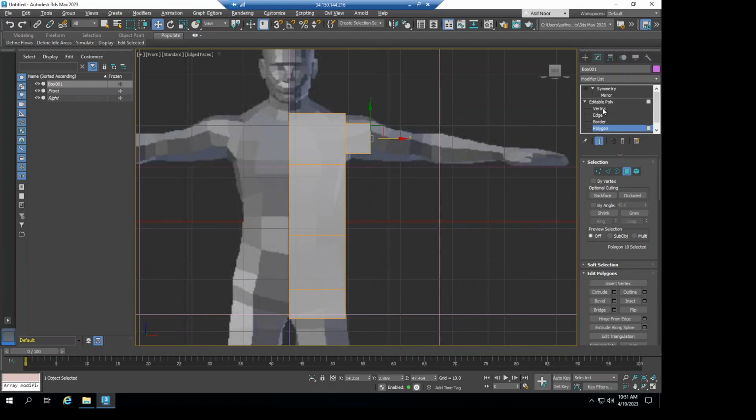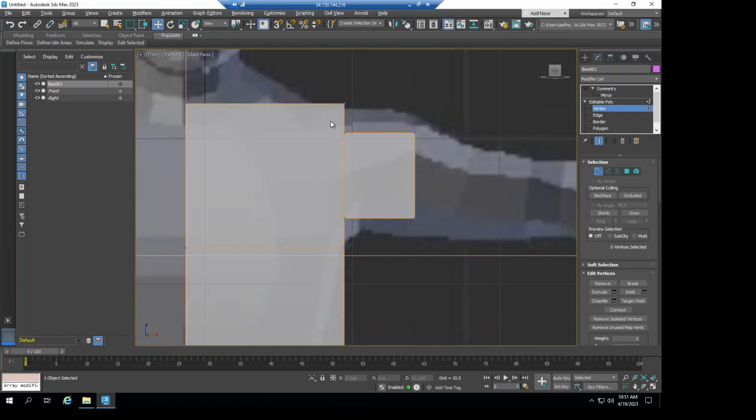It didn't come out the way I wanted it to be, but this is okay. So what I'm going to do is go into the vertex selection and select these vertices. Do Control Z and then click outside anywhere, and then maybe zoom in a little bit, and then box select these vertices, and then I'm just going to move them in this direction here maybe.